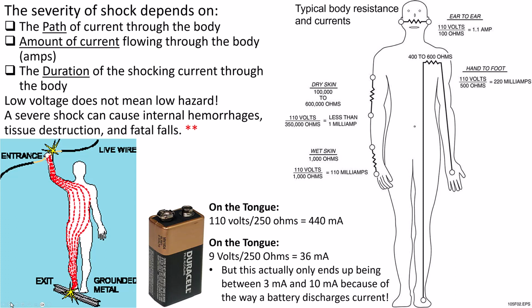I mean, that's not life-threatening, generally. Might change your taste buds for the day or something. But this picture on the right-hand side shows the idea that drier skin is not going to conduct as well. So you might, let's say, have 110 volts and high resistance, and you might only experience through your body 1 milliamp, something you couldn't even feel.